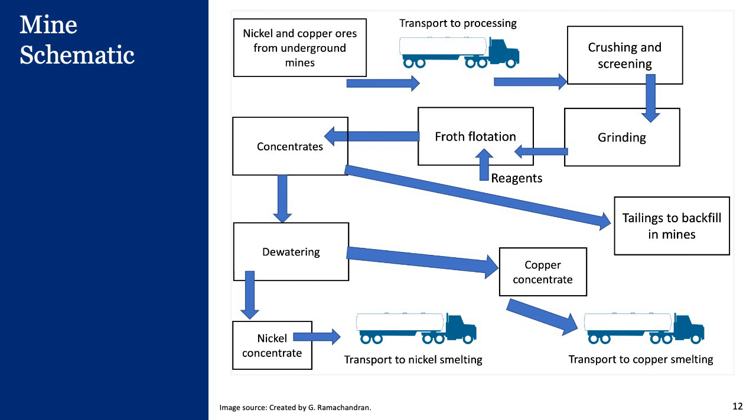And then you go into the grinding process. So here you're going to generate more fine dust. It's still a dusty operation. And then you add various reagents to it. Now we get into this area where you do what is called froth flotation, where you are mixing this powdered ore with liquids, and the metal bearing particles rise to the top of the liquid, and the waste or slag settles to the bottom in some cases.